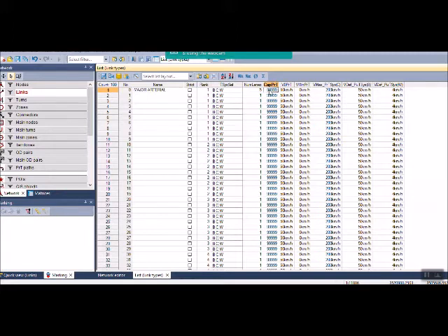But if you assume that the capacity of one lane is 1,000 vehicles per hour, 5 lanes will be 5,000 vehicles per hour. And the free flow speed on it, this is a major arterial, so I think it is expected to be 80 kilometers per hour.